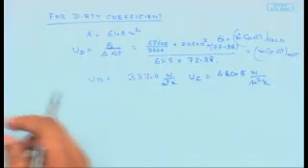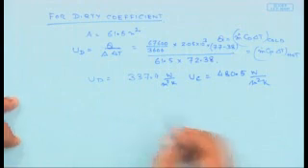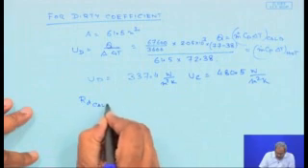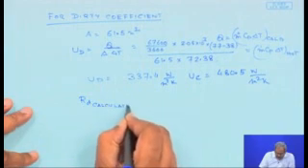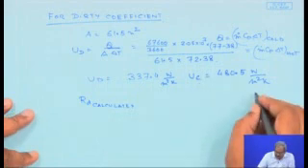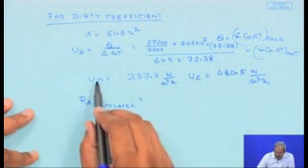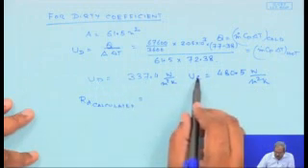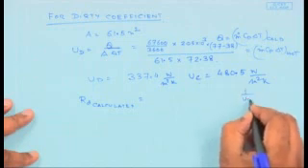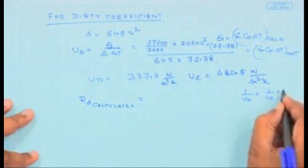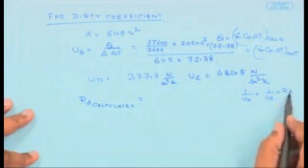So our next step then simply is to find out what is the value of the dirt factor. So let's see what this value would be. Your Rd calculated for this specific purpose, since I know Ud and Uc, 1 by Ud must be equal to 1 by Uc plus Rd, that is 1 by U dirty is going to be the resistance due to the clean condition plus Rd, which is the dirt factor.